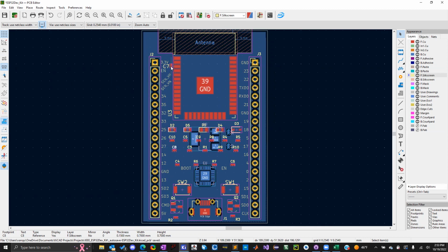Are you trying to filter it? What are you trying to do with that? I would say just make sure whatever capacitor you pick is rated for 5 volts. You shouldn't have an issue, but try and use ceramic as well. Ceramic capacitors are less noisy compared to electrolytic capacitors.